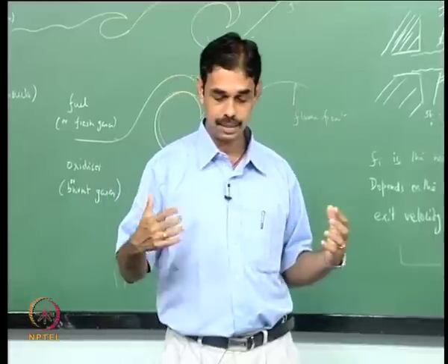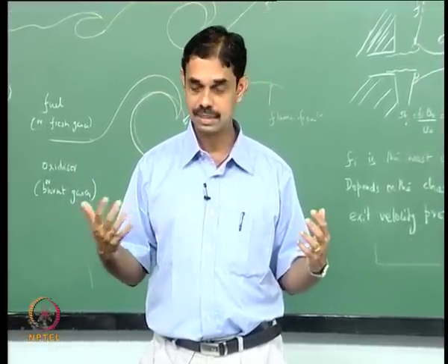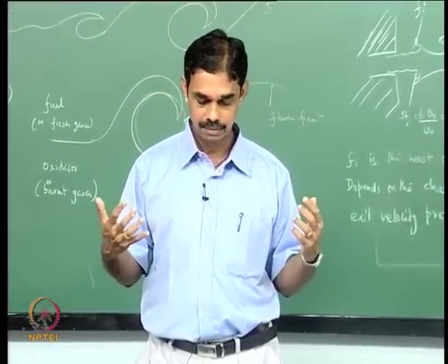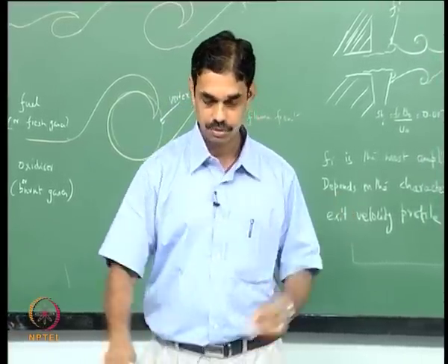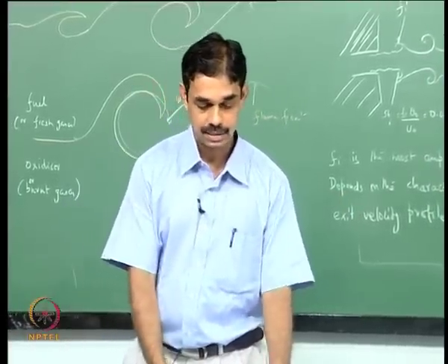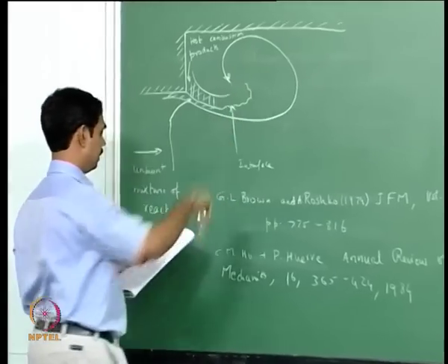So in the presence of large scale structures, we need to transition to fine scale mixing, and that is often initiated by the braids of vortices where high strain rates between the high and low speed streams exist, that is here, in these braids.